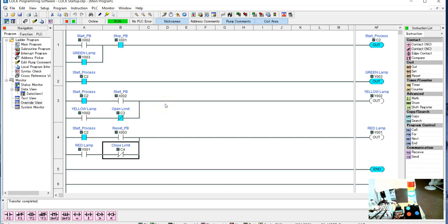And you will write a lot of programs in this fashion where you're going to have a signal that you turn on, and then another sensor or another push button or another memory bit or something that comes along later in time that tells it, hey, turn off. So that's a look at what you're going to be looking at upcoming. And we'll get into more of these circuits, and we'll start using some of the other devices that we talked about, with counters, timers, some of these sequencers and stuff.